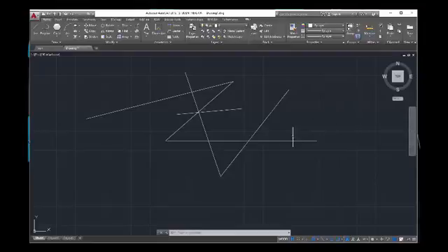Now I could click on a line to select it and then click on another line to select it. And I could click on all the other lines to select them all at once. That's one way, but there's actually a faster way. Hit escape to unselect an object. Now move the cursor towards the bottom right hand part of your screen. Click once, do not drag, but move your cursor up and away from where you clicked it.